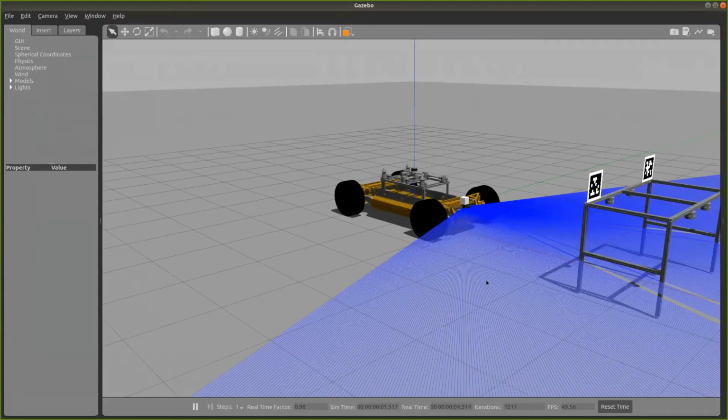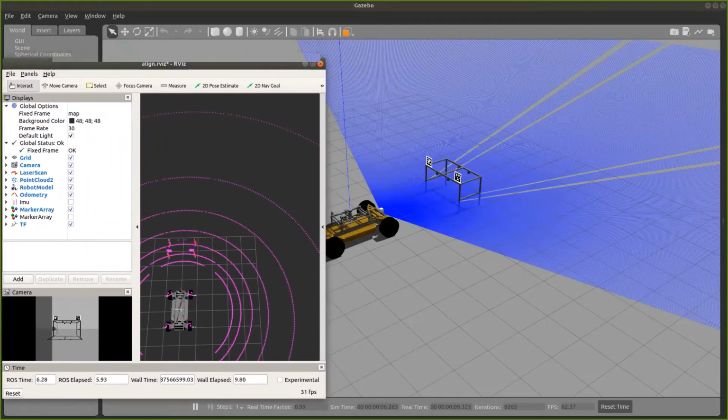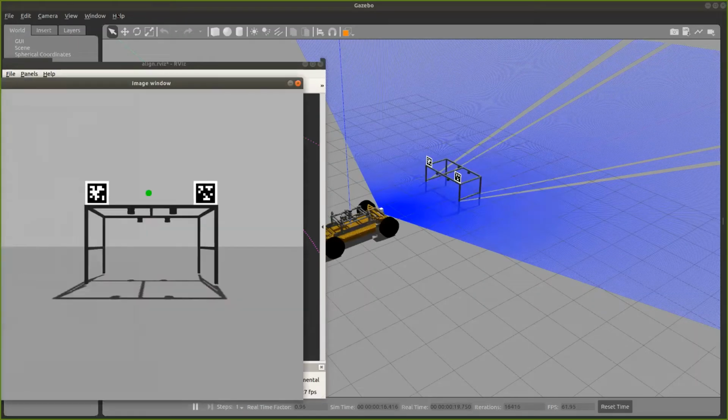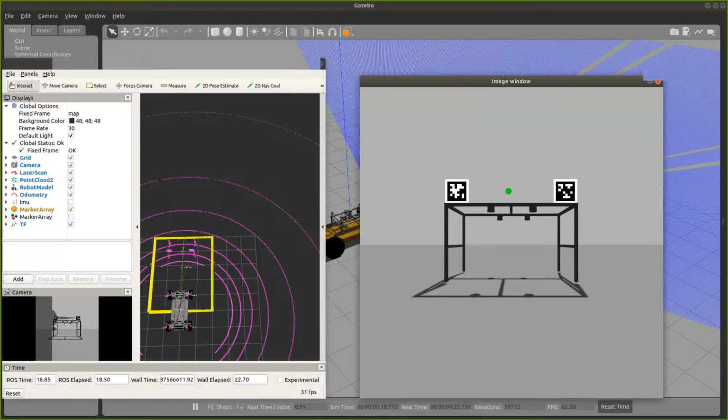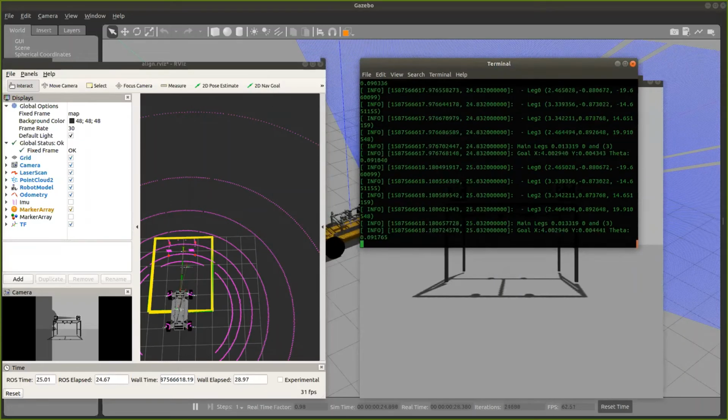Yeah, and this is what that would look like. The first set of things to do would be to launch the LIDAR-based localization and planning nodes and load the pod location prior estimate. These will be visible in RViz. So this is the image from the camera. And then in RViz, we can see that the yellow rectangle corresponds to the prior estimate of the pod location.